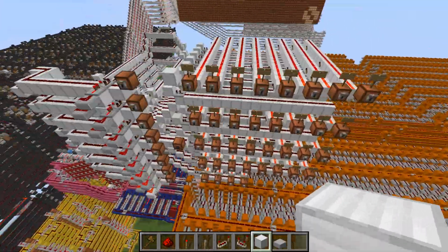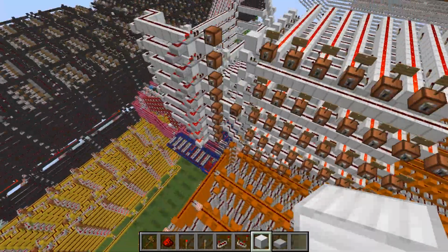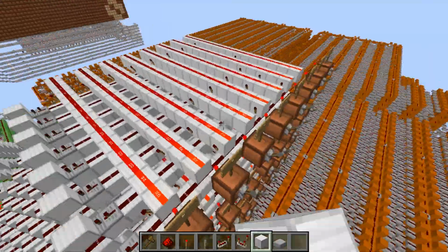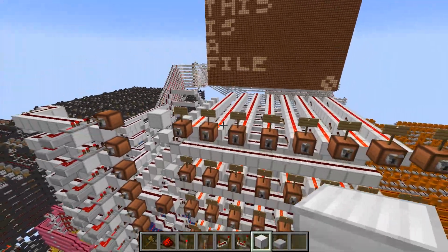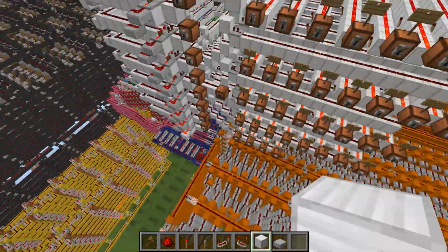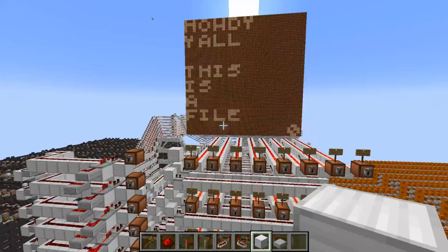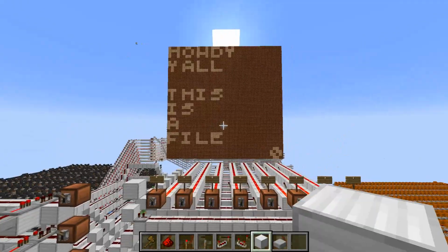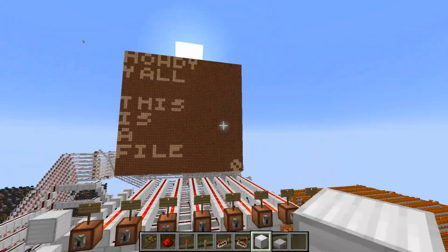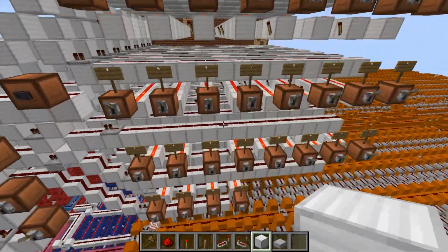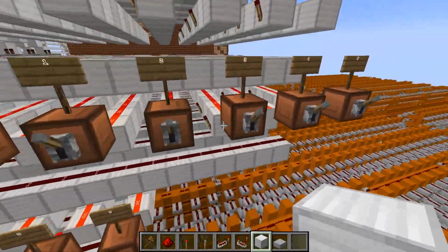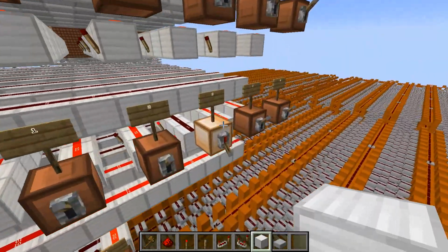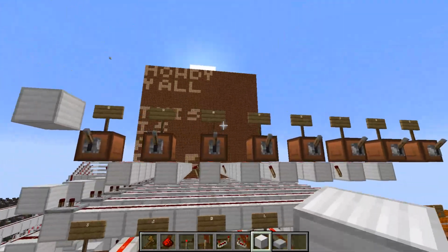What I first do is give it the character, and then I give it the position. So I have my keyboard, which is a really big encoder and turns my letter into an 8-bit binary number. And then I have a direct 8-bit input in case I want to give a very special character that I don't have on my keyboard, or for the special position. Let's say I want to put a 3 in that top right corner. So I would first select the number 3. So we have 3 right there, and then I press the button, and then it's loaded into the system, and then I give the position.